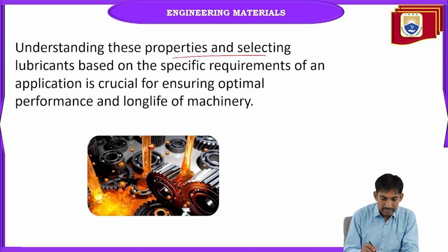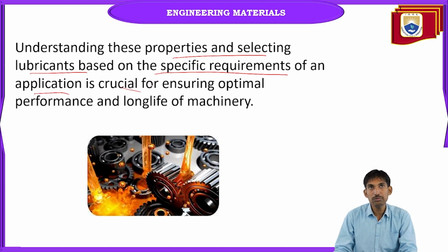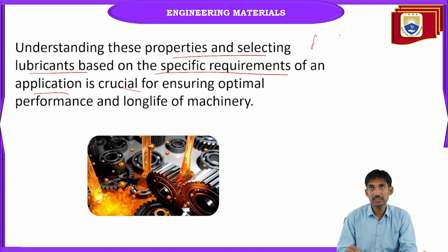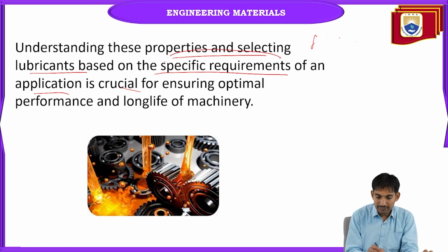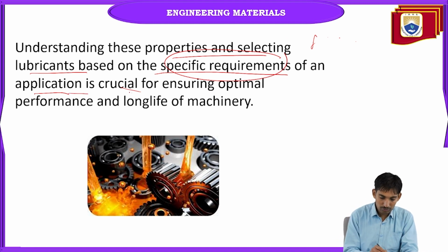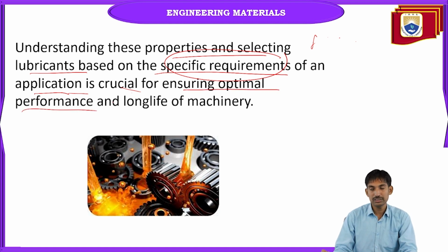Understanding these properties, like flash and fire point, viscosity, cloud and pour points, and oiliness, and selecting the lubricant based on the specific requirements of an application is crucial for ensuring optimal performance and long life of machinery.